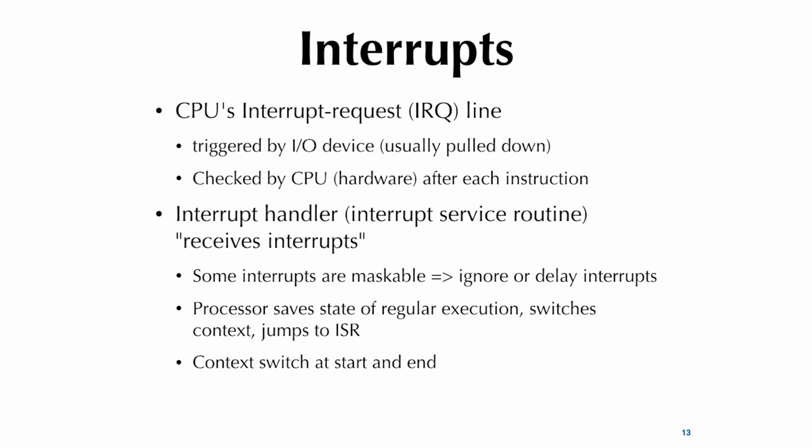Why? Because a pull-up is more of a soft one, and it's tied over a resistor. So if you pull it down to 0, what happens? Yes, you actually waste a little current, but the current is limited by the resistor, right? So you don't short circuit, okay? And it allows conflicting values to be driven on the IRQ line. So you allow some devices that are not asserting to just leave it pulled up. But as long as one device wants to request, it pulls it down.